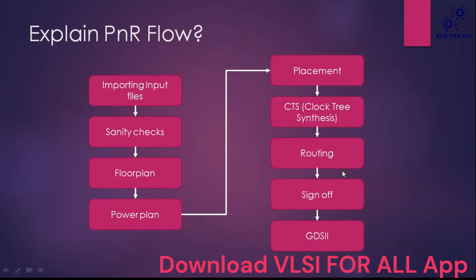They have to fix. If everything is clean, then GDS2. GDS means graphic design system. We have to generate that GDS and give it to the foundry. They will manufacture the design. I hope you people understood PNR also.